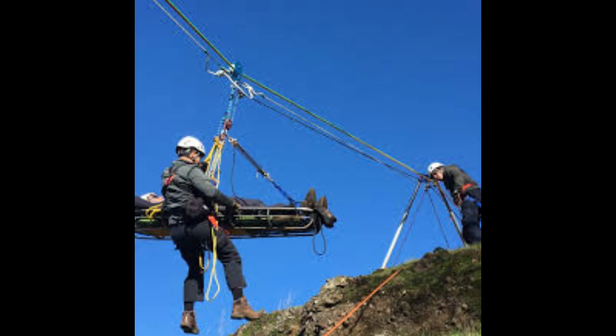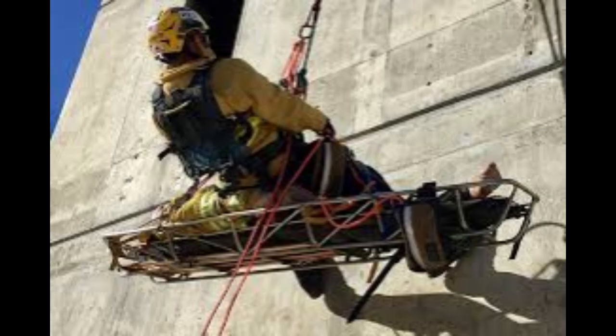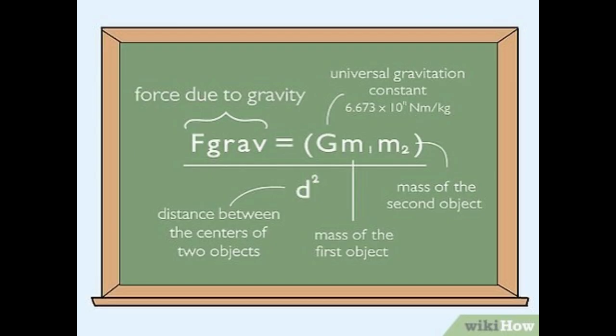We can calculate that force with this equation. Gravity force, or weight, equals 9.8 newtons per kilogram times mass of the object in kilograms. So a 70-kilogram rescuer hanging on a rope, 70 times 9.8, is equal to 686 newtons. That's the force the rope and system must support. Pretty neat, right? It's like a constant invisible friend who's always there, making your rescue predictable.